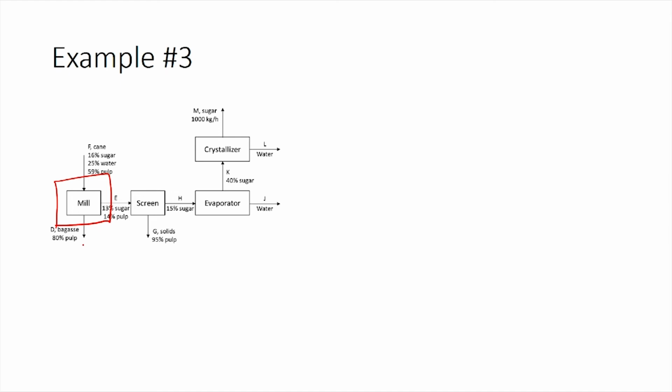So, just like how we solved the previous problem, here also we can make an assumption for the mass fraction of water in the stream to be XWD. Let us first start with the total balances. The total balance for the system mill would be F equals D plus E. We already know the value for E, which is 7819. So, F equals D plus 7819.